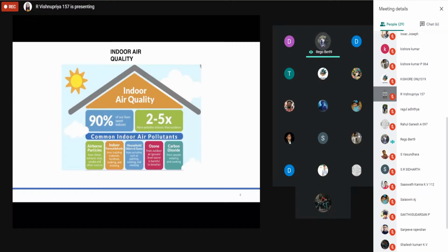See, for example, if you are going to paint an MS support or a steel kind of thing, we need a kind of oil paint. So the oil paint, definitely it's going to emit the VOC content. So that's where, in a building, after construction, when painting work is done, people will open the windows for maybe 3-4 days, because the complete thing has to move.